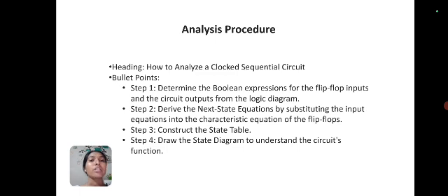Analysis procedure. How to analyze a clocked sequential circuit? Step 1: derive the Boolean expressions for the flip-flop inputs and circuit output from the logic diagram.